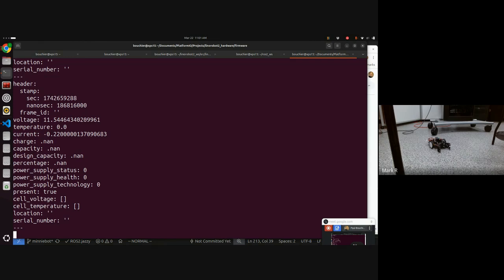When you brought up the robot and ROS on your laptop, it started publishing the syslog. So those syslog events, did you have to define them, or are they defaults that the systems have? They're in the firmware code. It's built so that there's a microcontroller version of log printf, and whatever that firmware prints is what comes up across the link to go into your syslog.